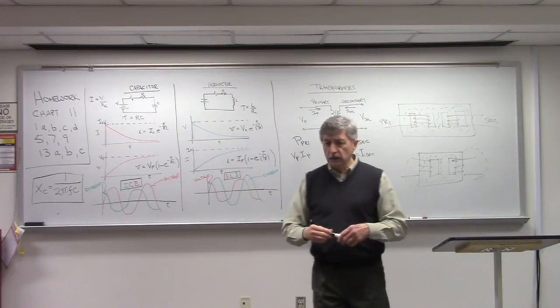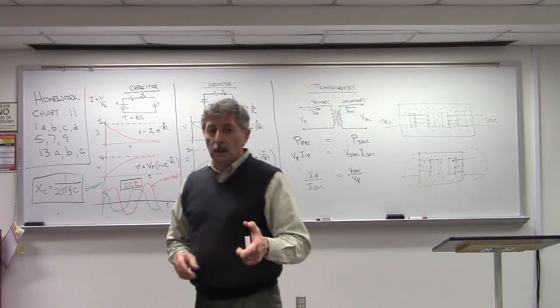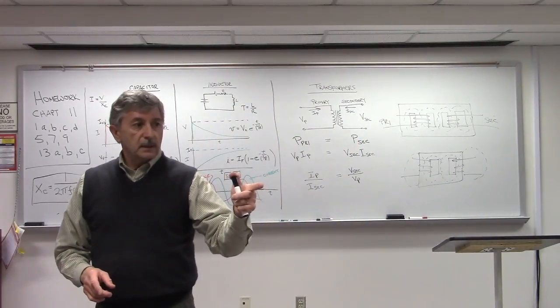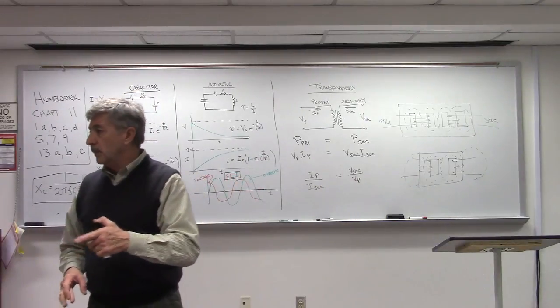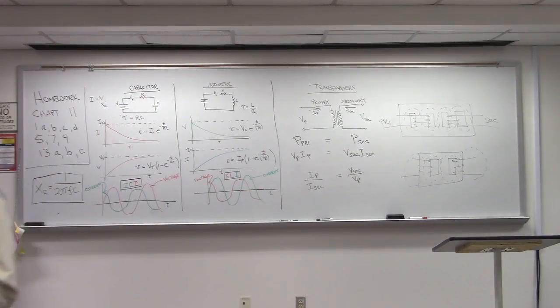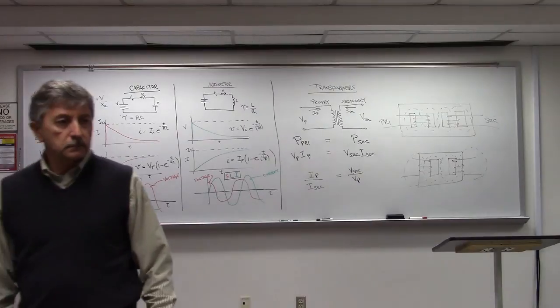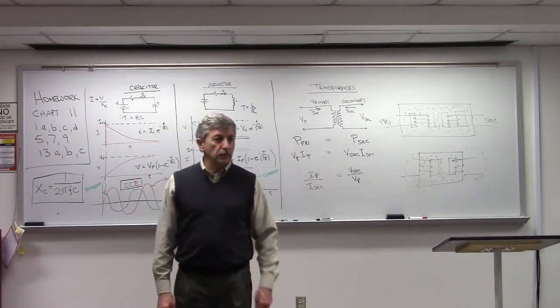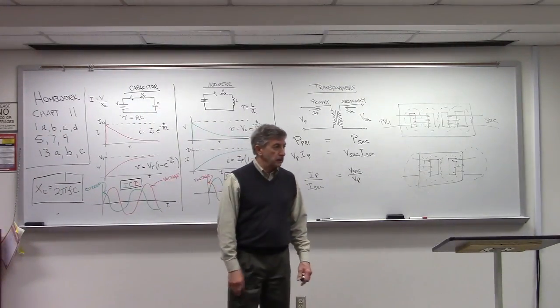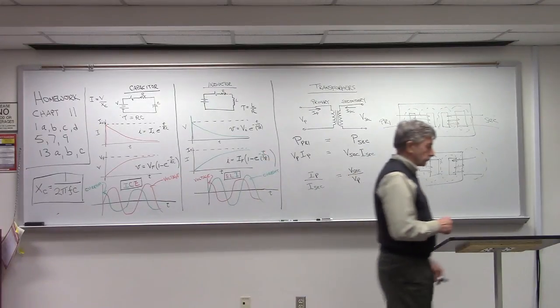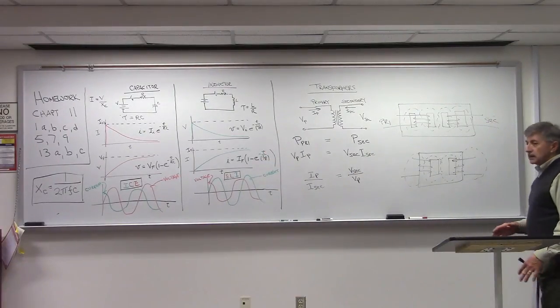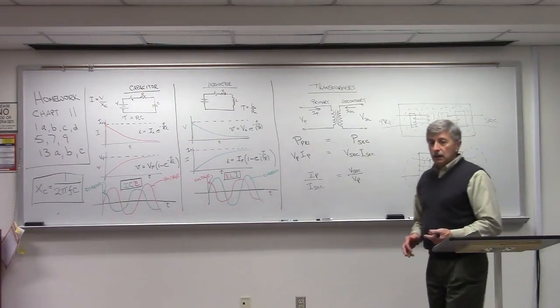And that's why on your transformers, you'll see that the size of the leads might show up a little bit differently. Where's the transformer? Yeah, on this one they don't. Some of them they do, some they don't. Some just use a minimum wire size and that's it, primary and secondary. They're kind of over-designed. But that's one of the things you have to take into account. If you're increasing